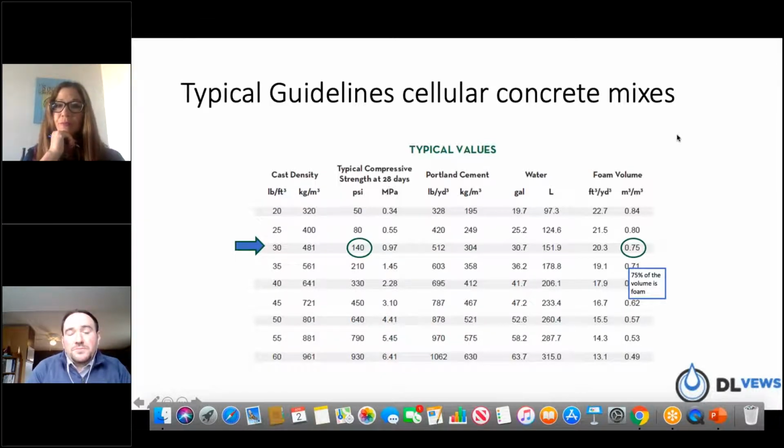Yeah, there may be some extreme cases where you need to, quote unquote, leak stop or help stop the leaks from becoming a nuisance for you. And in that sense, you might consider pre-filling those voids with some other type of grout, or waiting till a drier day, for example. Those may be other ways to tackle that annular fill.